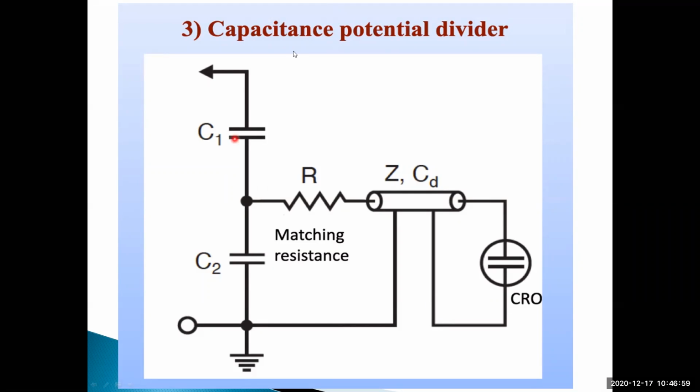Capacitor C1 is not a small value; it is a number of capacitors connected in series, converted into an equivalent capacitance called C1. When capacitors are connected in series, the voltage handling increases. Here the voltage across C1 is very high.